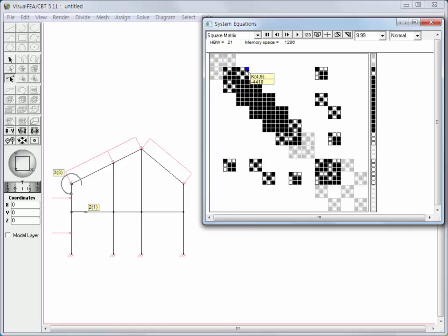The figures in the parenthesis are the row and column numbers of the matrix entry. The numerical value in the second line is the stiffness coefficient of the entry. At the same time, the degrees of freedom associated with the entry are indicated over the image of the frame model. A line arrow represents a translational degree of freedom, and a circular arc arrow, a rotational degree of freedom. In the case of off-diagonal entries, 2 degrees of freedom are represented by 2 arrows.